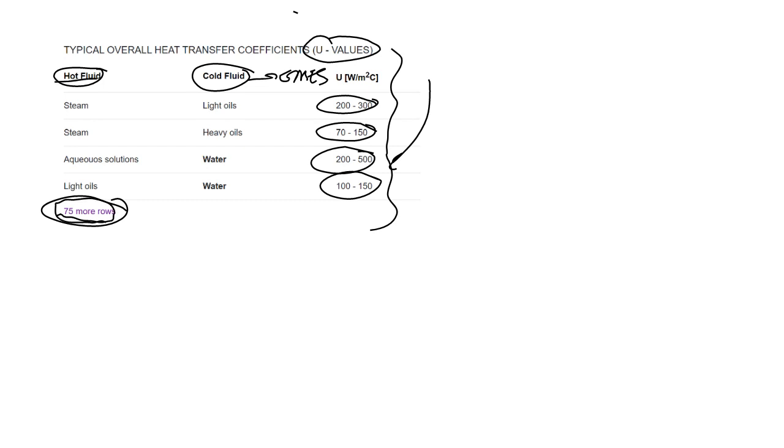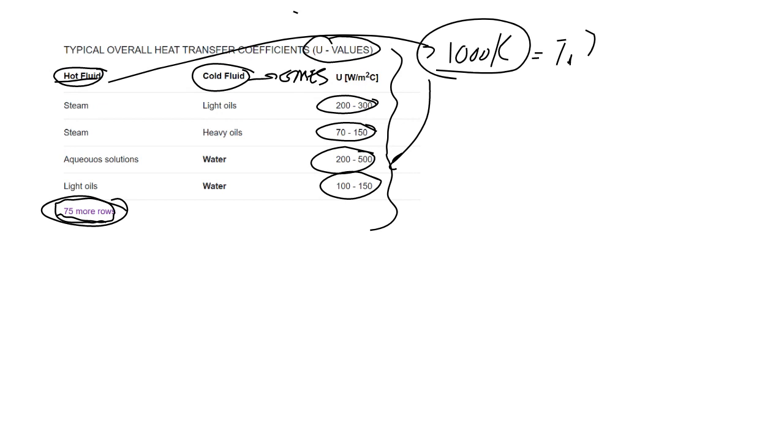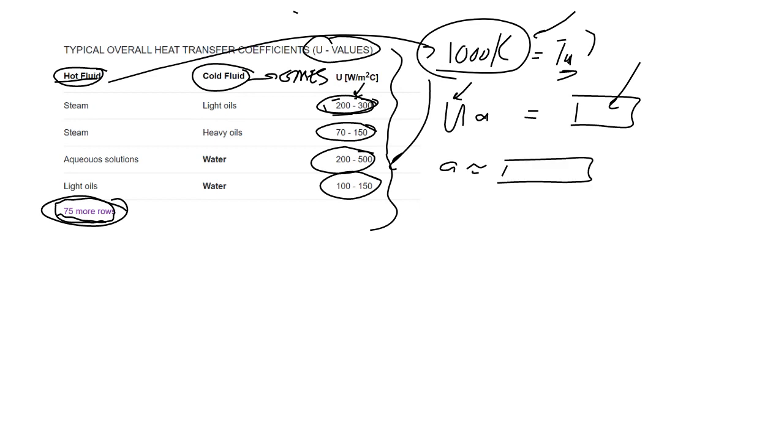And what is your hot fluid going to be? That hot fluid that Vogler wants you to use must have a temperature of 1000 Kelvin, the utility. So you will have to do some independent research to see, can I find a utility with this high temperature? And if I have that, what is a typical range of U values? And if I now use a typical range of U values, and Vogler says that his UA is whatever, and I choose that, his A, in other words, is whatever his A is, and is that realistic? What does it imply for how his reactor will look?